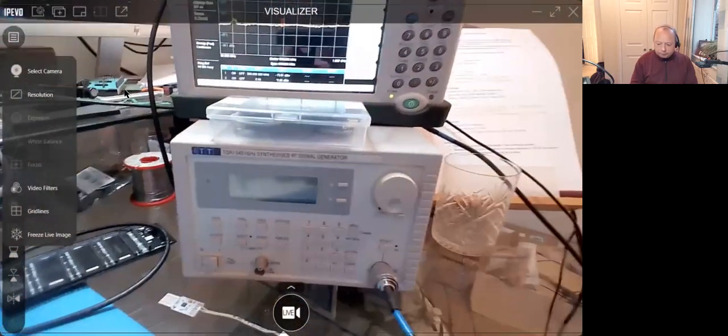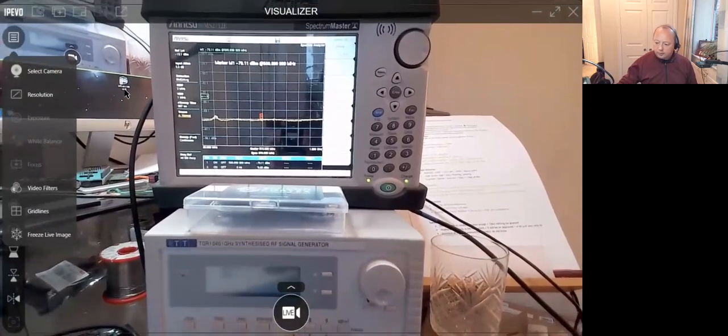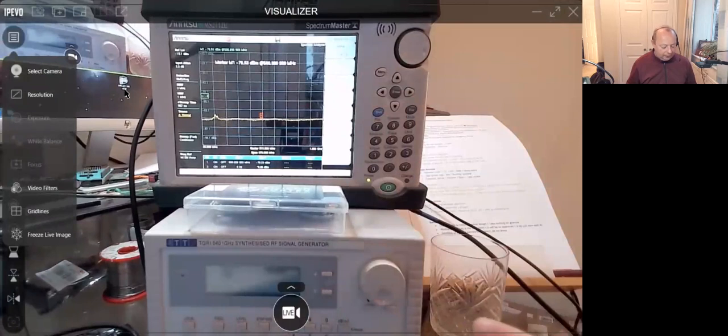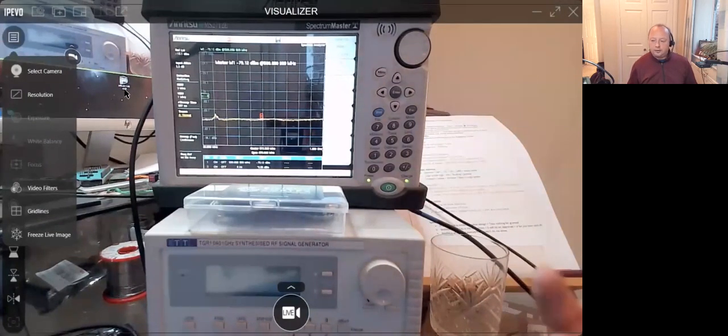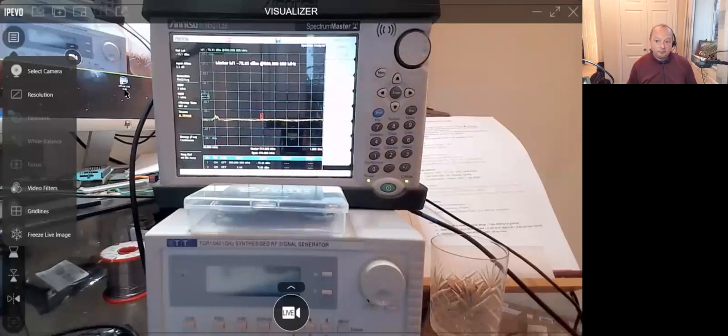So I've got here an actual spectrum analyzer. That's what this thing here is. When we're designing electronics, as long as there's no Bluetooth or Wi-Fi, we'll usually be looking for problems in the 30 megahertz to 1 gigahertz range. If you've got Bluetooth, as you do on a Raspberry Pi and a lot of wearable electronics, which is 2.4 gig, you're going to have to go up to 6 gigs worth of looking for problems. And interestingly, because battery products are usually very small, you tend to start to see the problems at the very high frequencies. Certainly in the project I've been working on for the last few weeks, a very small wearable device with Bluetooth, we had problems up at the 4 to 6 gigahertz region. And that's not uncommon.